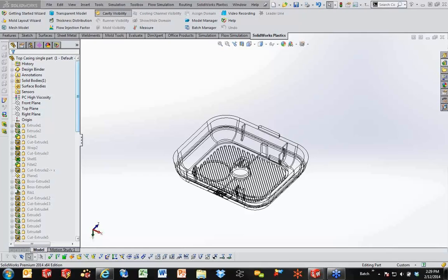Oh, we got one more. Could you import an STL file and design and edit the mold? So we're not really doing anything with the mold itself. Any way that you can get geometry into SOLIDWORKS, we can see if it will fill with the pressure and material that you've chosen. So yes, we could bring in an STL, and yes, we could see if that STL would fill, but we're not really doing anything with the mold.